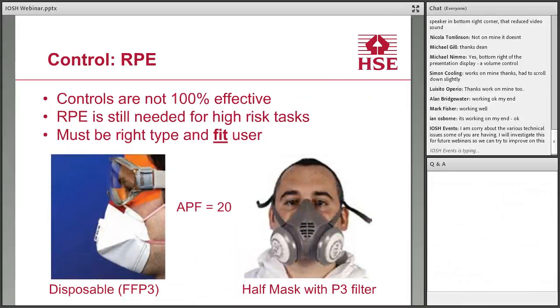I mentioned that they're not 100% effective, so RPE is still needed for some high-risk tasks, and what we've tried to do is give guidance on where that is the case. Probably out of all the things that I get asked on dust, RPE is probably the most frequent and the most varied questions. The two things we stress is it's got to be the right type and it's got to fit the user.